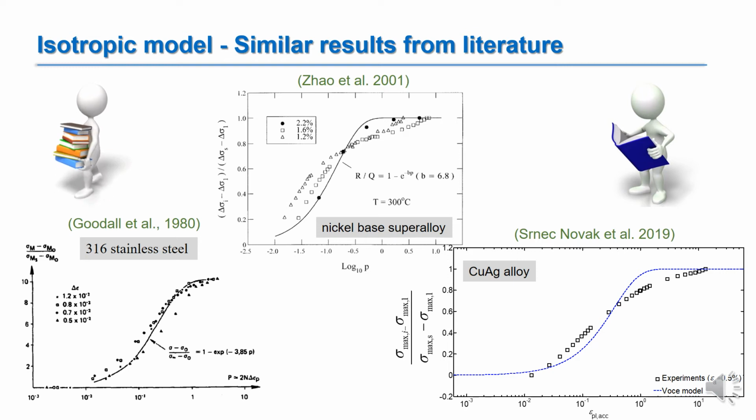Similarly, like in the case of the chromium molybdenum, the Voce model was able to fit precisely the behavior of material for the first and stabilized cycle. Other than that, the model follows a trend that deviates significantly from the trend observed in the experimental data. With the aim to improve the fitting accuracy, we modified the evolution of R in a new isotropic model.